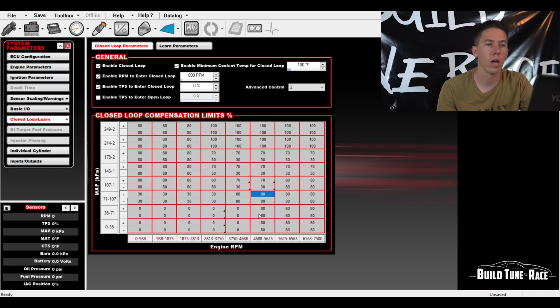But with the way that elevation changes, density, altitude, and everything, you might as well use the EFI system for what it is and at least allow it to correct maybe 10%, maybe 20, maybe 20% rich, 10% lean. So then it can add some fuel if something happens and it needs it. So a lot of times, unless there's something weird, kind of with what happened on my last setup, I only see about 4 to 7% adjustment pass to pass to pass. So when you get down to those kind of numbers, you know you could put a 10 to 15% correction in it, and it really will never get past that unless there's an issue.